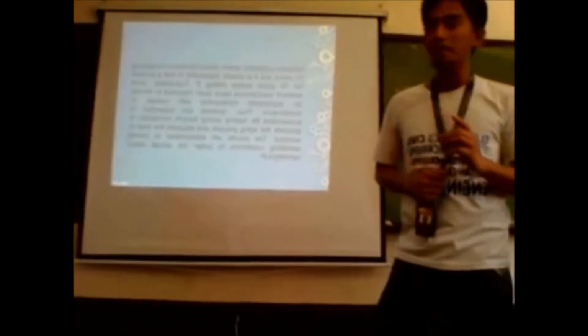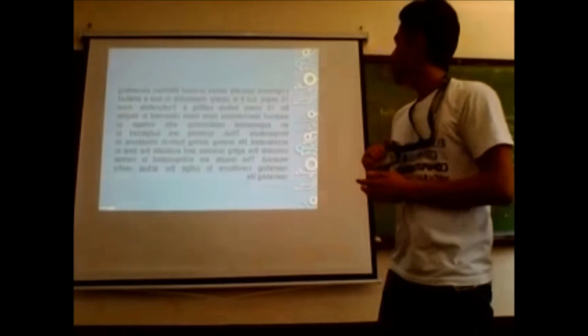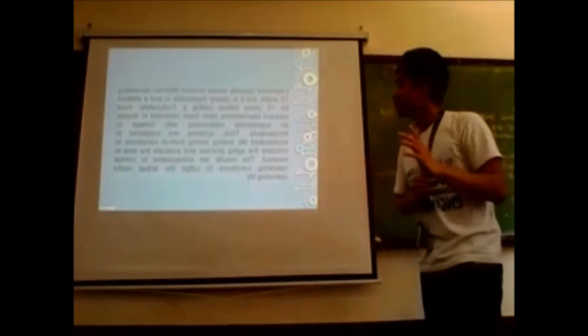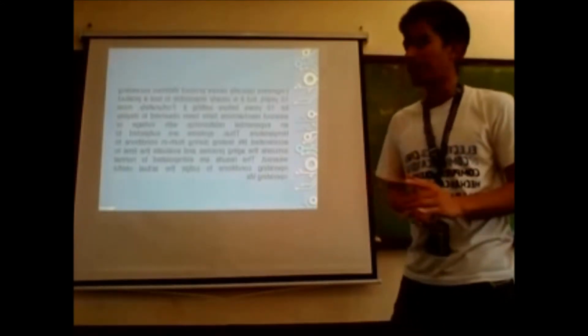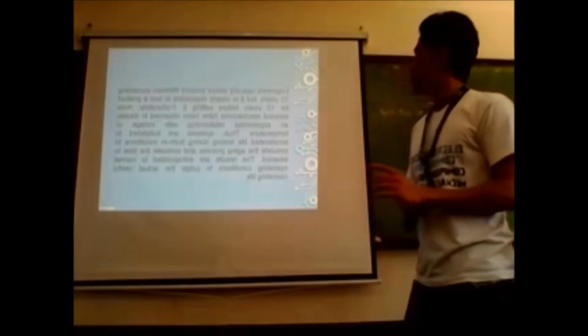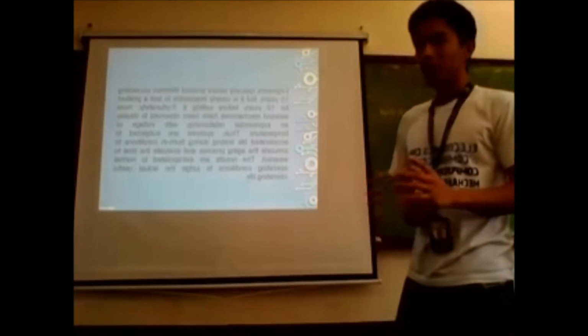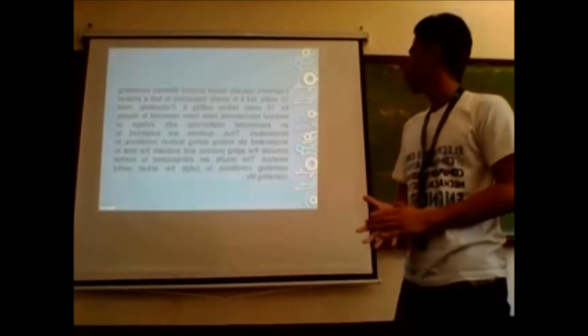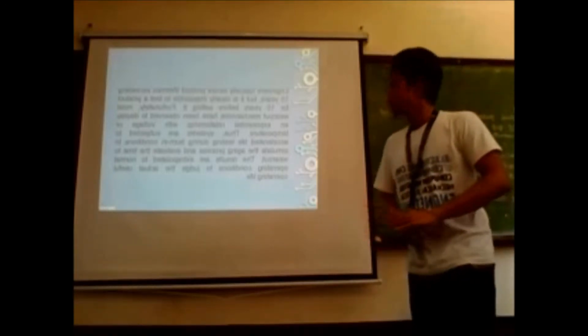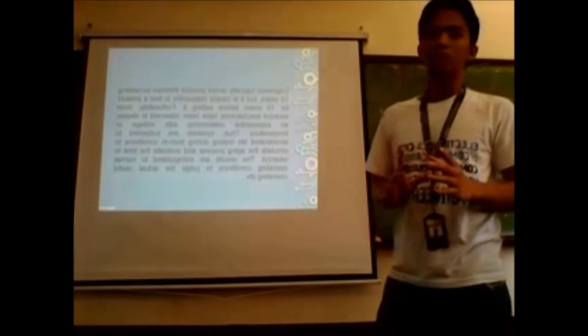Thus, systems are subjected to accelerated life testing during burn-in conditions to simulate the aging process and evaluate the time to wear out. The results are extrapolated to normal operating conditions to judge the actual useful operating life.